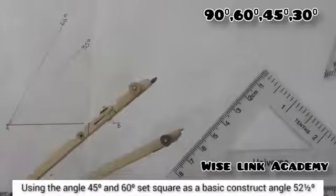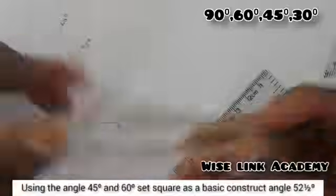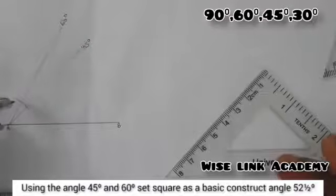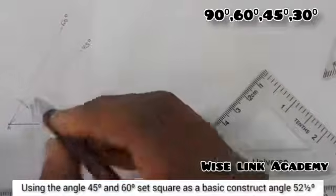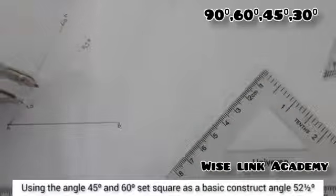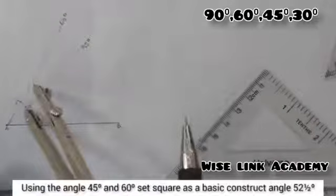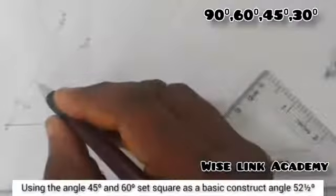So I'll take my compass at this point, any radius of your choice. Come to this point A, strike an arc here, just cut the arc this way. Let's call this point A prime and this point A double prime. So come to A double prime, strike an arc this way, and then come to A prime at this point. Where the arcs cut is at this point.